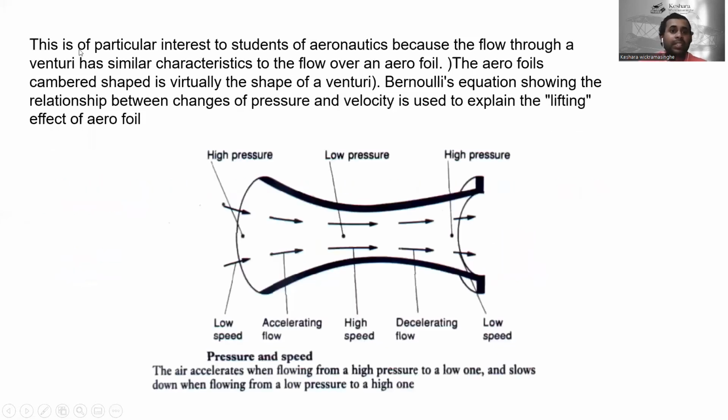Okay, this is of particular interest to students of aeronautics because the flow through a venturi has similar characteristics to the flow over an aerofoil. The aerofoil's cambered shape is virtually the shape of a venturi. Bernoulli's equation, showing the relationship between changes of pressure and velocity, is used to explain the lifting effects of an aerofoil.